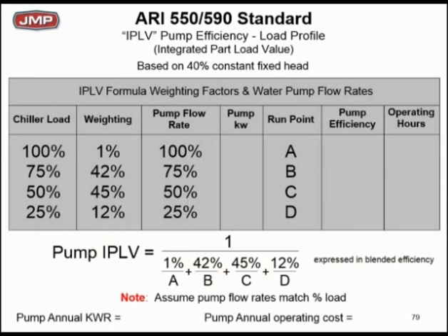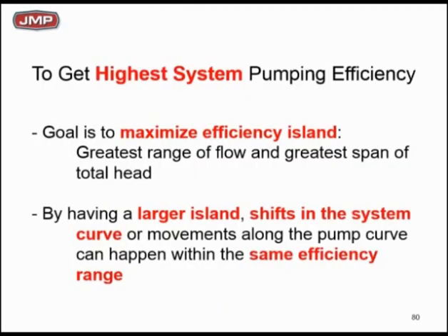What could be wrong with that? Everybody already understands the load profile. If you got your own load profile, load that in. If you don't, then let's use the standard load profile that every pump vendor can get a hold of. Everybody understands, and we can use their coordinates to get the highest system pumping efficiency, to get the lowest kW electric bill. Make these islands as big as you can. So as you shift back and forth, you keep that average weighted efficiency higher.